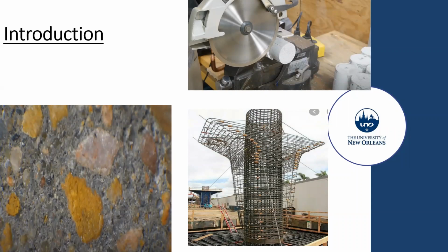So if you use cement rather than rocks and sand, it's going to be costly, right? This saves cost, but the aggregates also improve the structural properties of the concrete by increasing the strength and reducing the amount of shrinkage as the concrete cures.